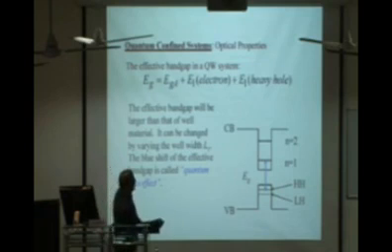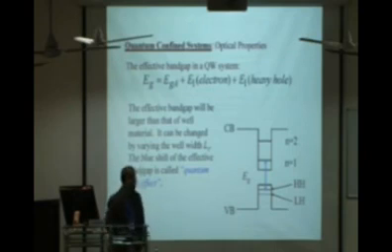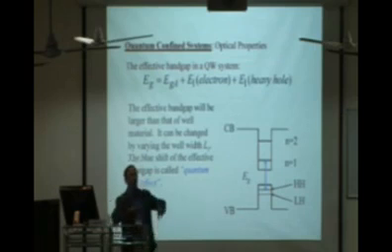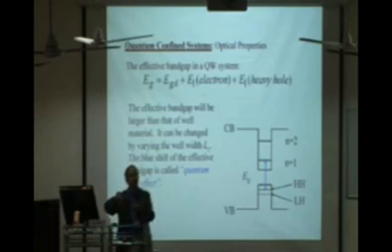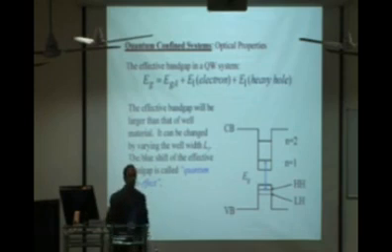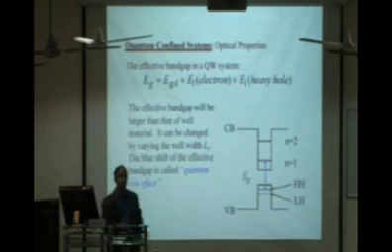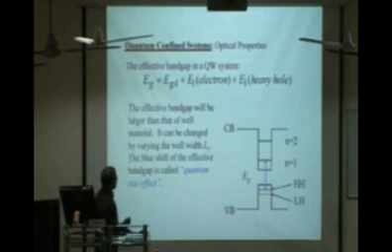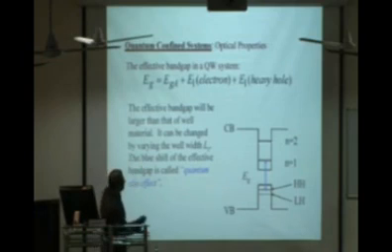And if you have a very high barrier, you can confine not only the ground state but some of the other states also. In fact, this is also a challenge. It is not very easy to get a combination of a low band gap semiconductor with a high band gap semiconductor so that you get a very high barrier height and confine many energy levels. Theoretically it is possible, but experimentally it is very difficult because there are a lot of problems in the growth of semiconductors with different lattice mismatch. But anyway, what we can say about this quantum size effect is that as we reduce the size, it goes as 1 over L squared, and the spacing increases. So basically you can tune the band gap of the material.